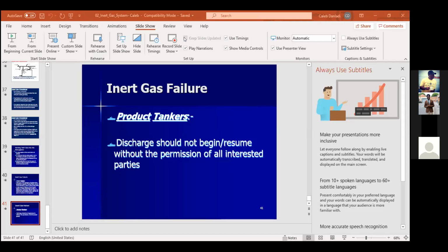When I was a chief officer in NLNG, I went to Mogadis. What they supplied us was nitrogen. On completion of dry docking, they supplied us with nitrogen to the tank from shore. Trucks were coming. And then when we went, we didn't have to do anything. We just did our normal extended cooling down, because at that point, you don't even need to gas up. We use nitrogen on the LNGs for primary and secondary barrier space, exactly.